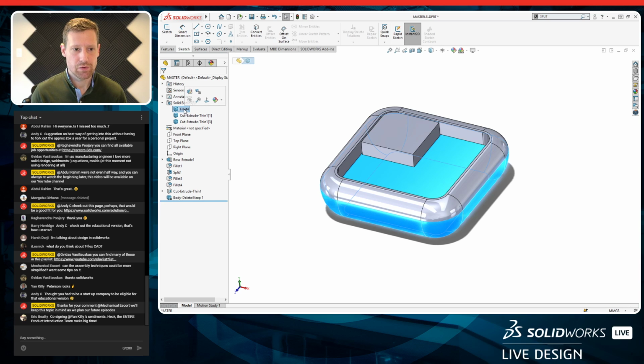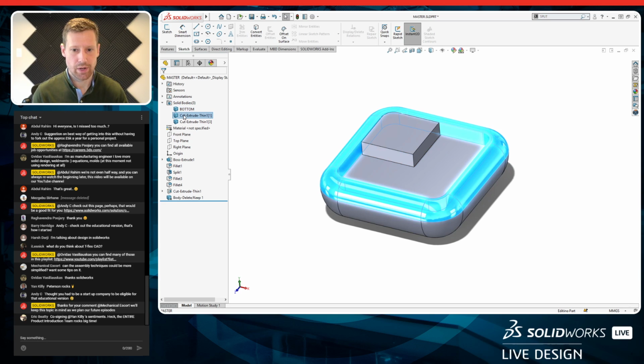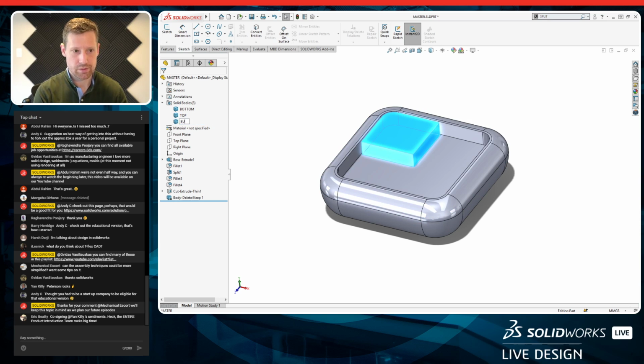Okay, so with the rest of these, let's start giving them some names here. So for this one, I'll call this bottom. It's always nice to rename these, and we're going to use this renaming later. We'll call this top, and we'll call this button. Okay. And while I'm here, I might as well add some materials. You may not know, but you can add materials instead of to the whole part, you can add them to individual bodies.